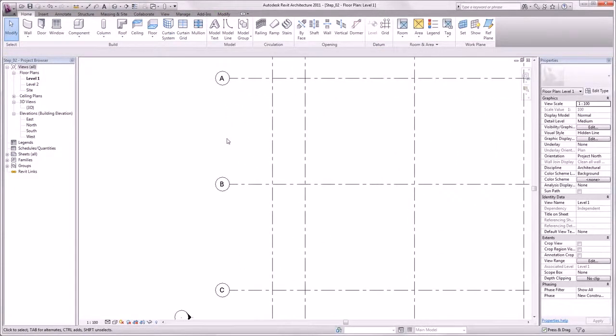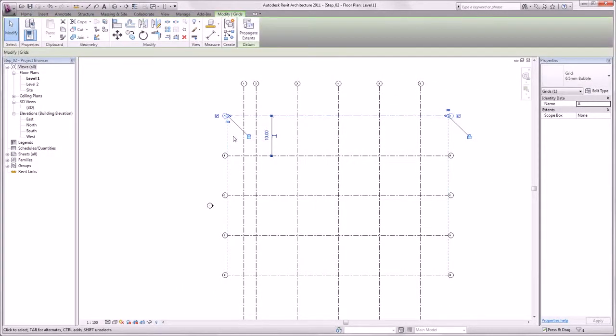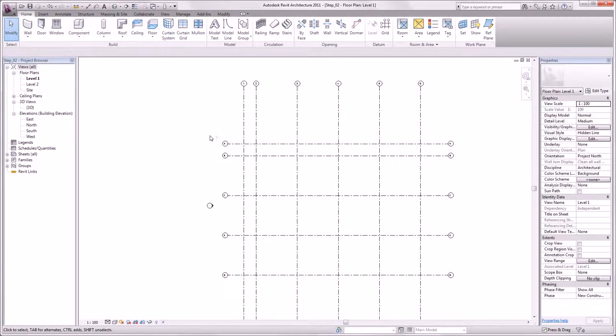And you also see Revit names the grid lines properly. Now we select our A grid. You see here a temporary dimension. Everything which is blue in Revit is changeable at any time. So we click and we change 10 to 3 meters. So we now have a distance between the A and B grid of 3 meters. We repeat this over here.